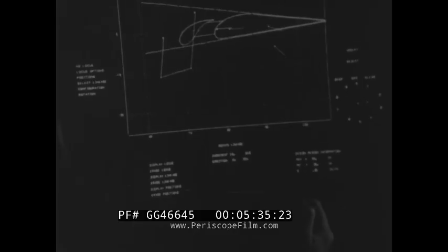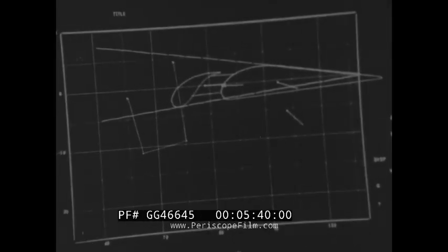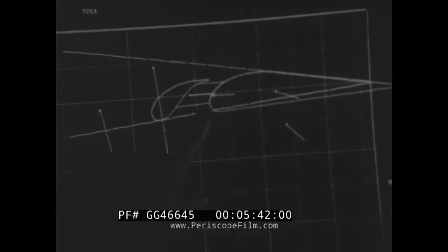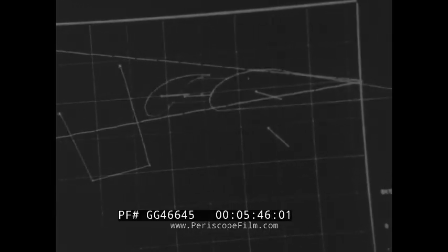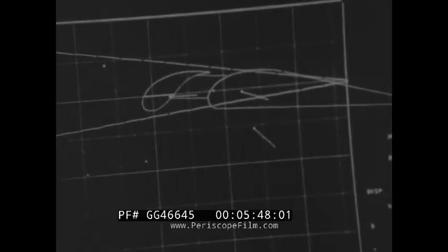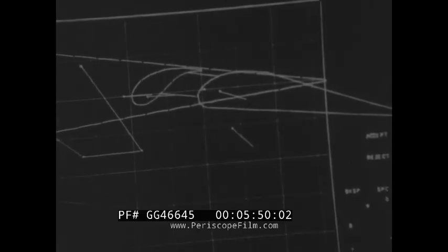The light pen switch can now be used to trigger the motion. Each time the switch is depressed, the linkage and flap configuration move one increment in the specified direction. The items constructed are seen to maintain their original relative positions, but together move aft, exhibiting Fowler motion.